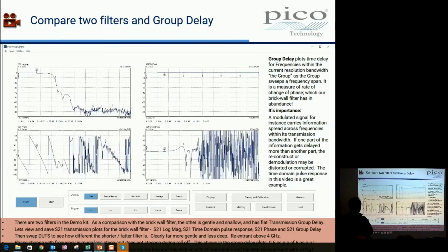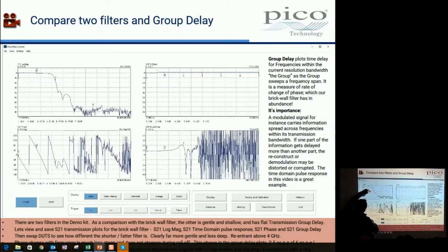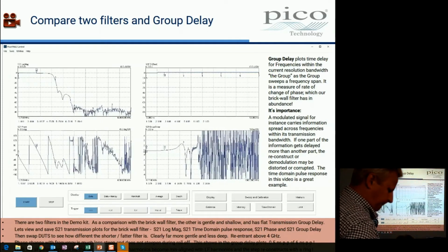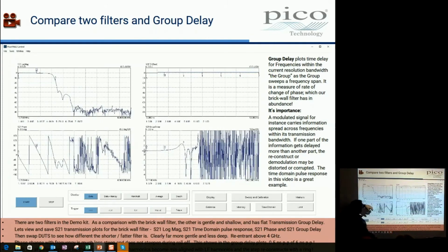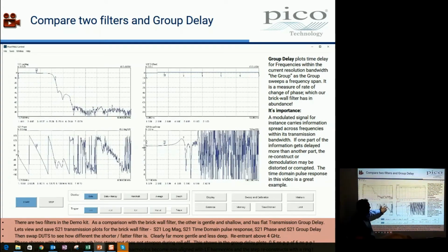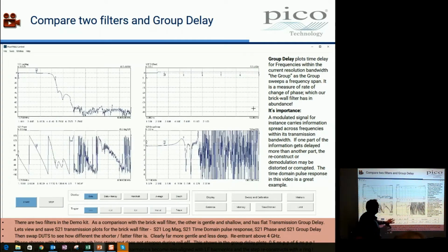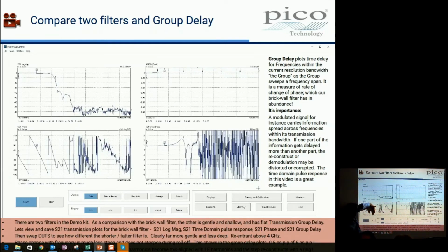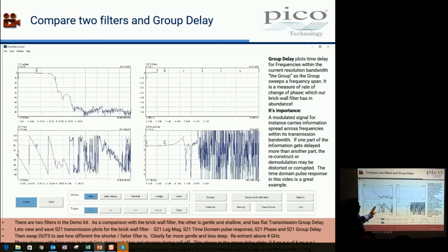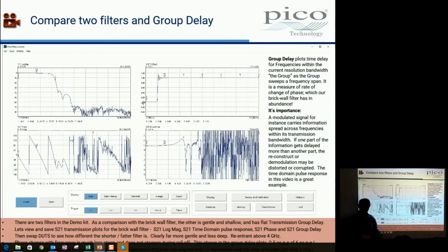Now what have we got here? We've got the roll-off point, and we can see at the roll-off point phase goes absolutely AWOL, and then we roll off into the noise and phase information becomes indistinct. We saw this the other day, didn't we? We've got a group delay plot that is showing that the slope of phase is changing a lot, and we've got a nanosecond of delay overall.